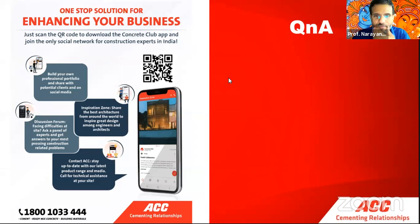What's the role of reactive powder? Reactive powders will react with the calcium hydroxide formed from cement hydration to give you secondary CSH. I will show that a little later. What may be service life of UHPC? I have seen numbers up to 100, 150 years, but since we don't have that for that long, we don't know what it is yet.